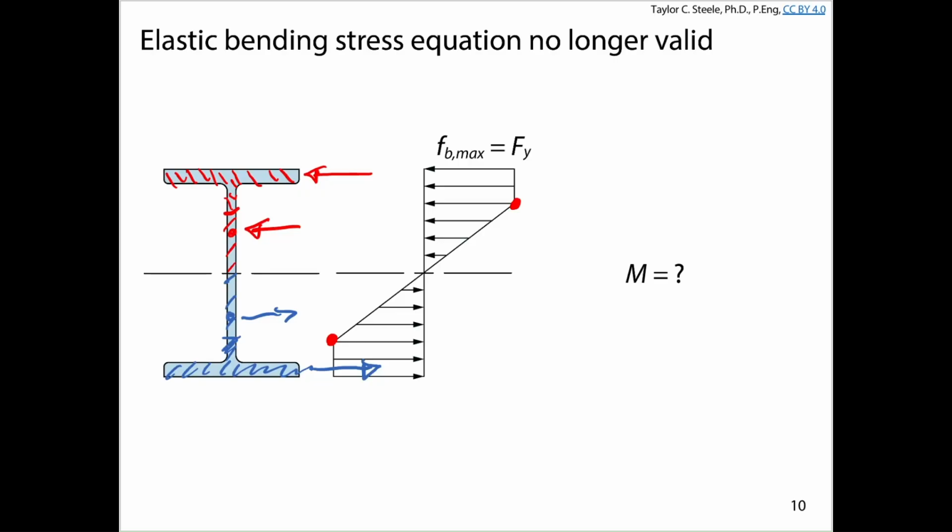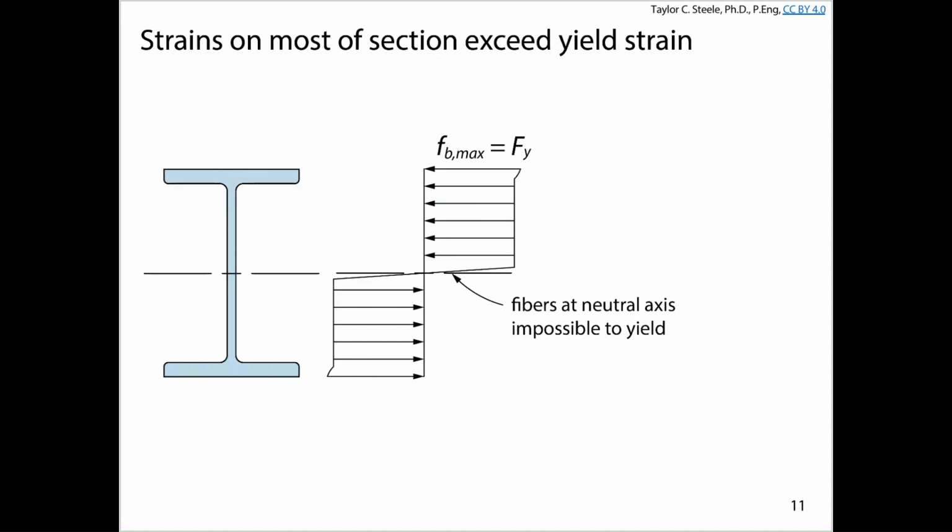Now, steel is really ductile, right? So we saw that this is sort of the linear elastic range, and then we have a yield plateau. Well, the yield plateau can continue on for a significant distance, right? And so what we can actually do is continue to increase the strain on our beam until we get to a point where we're not going to get a significant amount of additional bending moment strength out of that beam, right? So this is basically the linear elastic part, this is the yield plateau, and this is the region where we start to get a little bit of strain hardening.